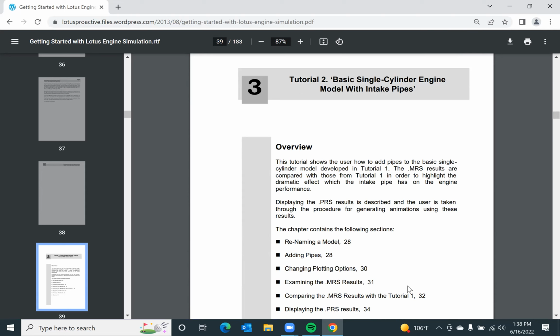The textbook method that we are using is just to give us some preliminary dimensions of the engine. This is the bore, this is the stroke, this is typically the crankcase diameter, this is the type of piston we are going to use, this is basically the size of the connecting rod, this would be the section of the connecting rod. But if you want to get into the detailed design, manufacturing, production, you will have to resort to the design simulation softwares. Everyone understood this?